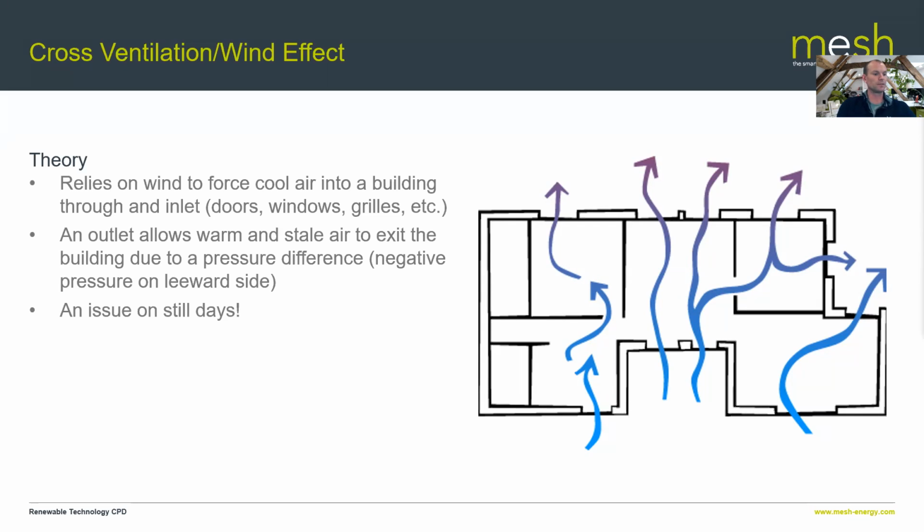So we've all been, you know, in buildings where it's hot and muggy and there's no wind and it's an absolute killer. That's where a blend of these things in building design really comes into its own, because using the stack effect or the buoyancy effect works absolutely fine on non-windy days, because you've got warm air rising and you don't need wind for that to work. So have a think about mixing some of these things in building design to really cater for year-round performance.